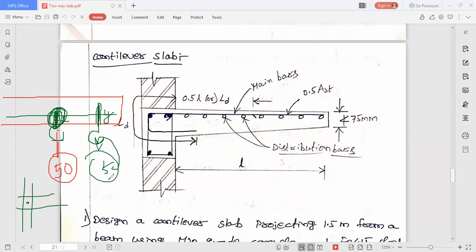That's why it is safe against 50 kgs of applied force. Okay, so whatever the length you have provided, whatever the depth of embedment you have provided in the concrete to resist the applied force, that length is called development length. Remember this carefully. Development length means the depth or the length of embedment of the steel bar into the support, that may be a slab or beam or anything. The embedment of the steel bar into the support to resist the application of load is called development length.